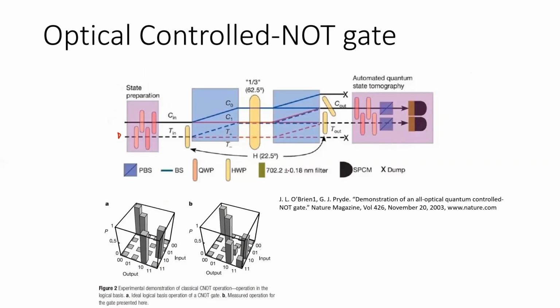In addition, there is one more thing we can eliminate from this design, which is the filter. The filter is meant to preserve only the light source that they are sending, which is 702.2 nanometer, and to reject any other photon. The reason is that they want to make sure no other photon will reach here. Again, guys, our idea will eliminate this because we are not really interested in one single photon. In our project, trillions of photons will pass, and that's okay because what we will put here is a photometer to measure the intensity of light.